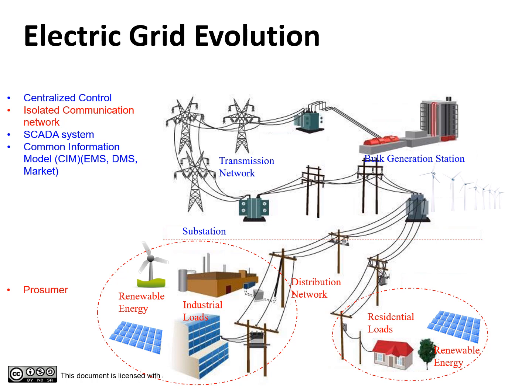In order to control renewable energy resources integrated into distribution networks, communication and SCADA systems must be extended to cover the distribution networks. Centralized control is feasible with small numbers of bulky generation stations, but controlling large numbers of renewable generation units installed over a wide geographical area from a central location will be very challenging.